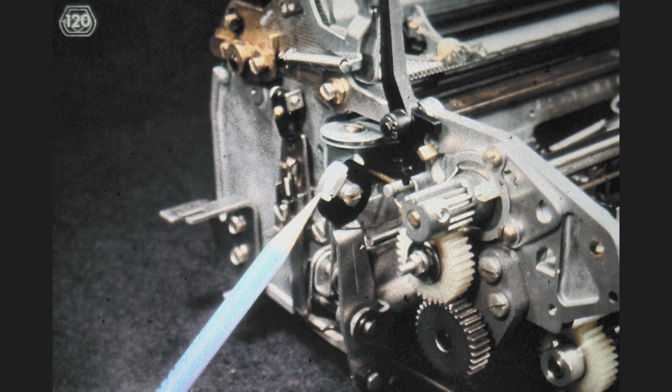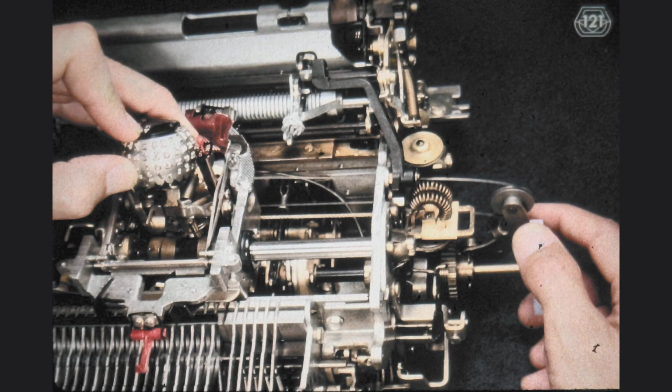Do not make this angle any smaller, because the shoe might otherwise interfere with the tape when the rotate arm sweeps clockwise, all the way into the -5 rotate position. The same is true for the +5 position of the rotate arm if the angle is much greater than 150 degrees. Our first step in the reinstallation of the rotate tape onto the rocker is reloading the rotate spring.